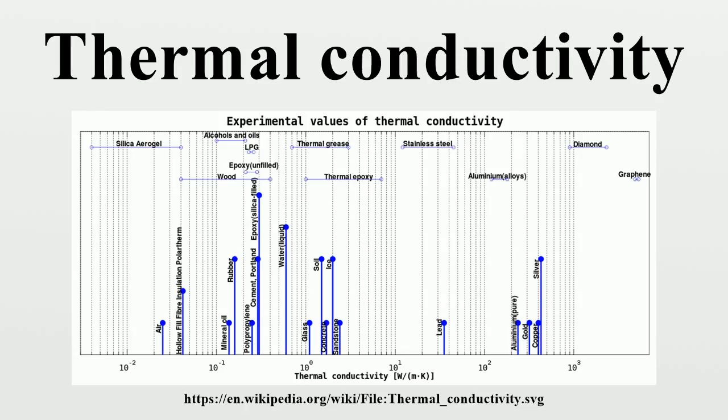Definitions. The reciprocal of thermal conductivity is thermal resistivity, usually expressed in Kelvin meters per watt. For a given thickness of a material, that particular construction's thermal resistance and the reciprocal property, thermal conductance, can be calculated. Unfortunately, there are differing definitions for these terms. Thermal conductivity, K, often depends on temperature. Therefore, the definitions listed below make sense when the thermal conductivity is temperature independent. Otherwise, a representative mean value has to be considered. For more, see the equations section below.